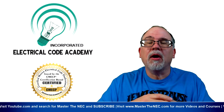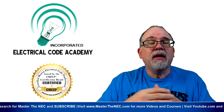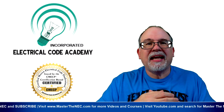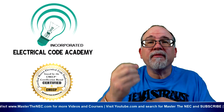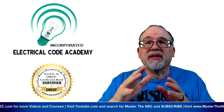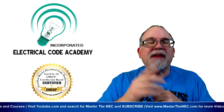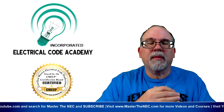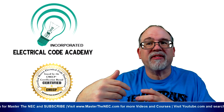Okay. Now, what about a delta to delta 3-wire secondary? Under that rule as well, if I have a delta to delta 3-phase transformer setup and the 3-wire secondary of that transformer only has one voltage value, like a 480 or a 240, and that's the only voltage value on that secondary, then that primary overcurrent protection could protect the secondary of that transformer. That's the only rule here when you're not dealing with protection on the secondary.